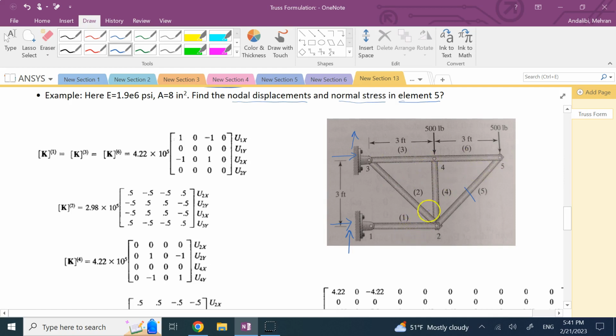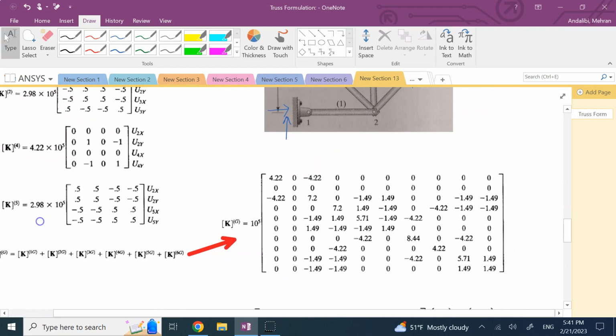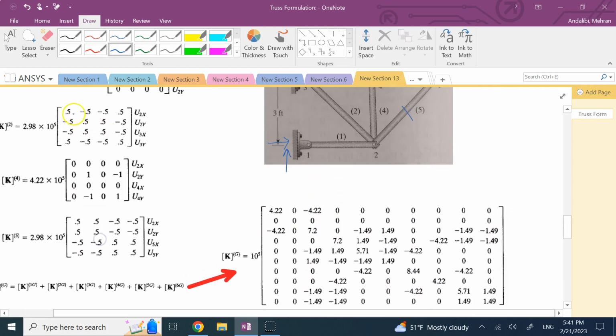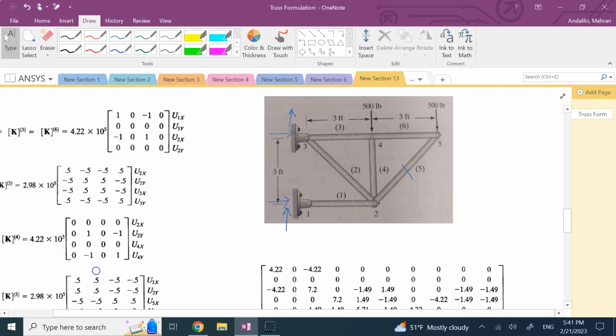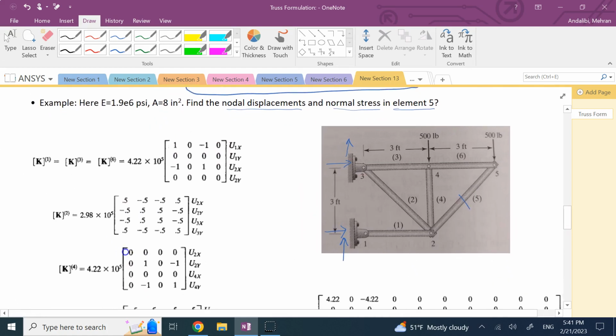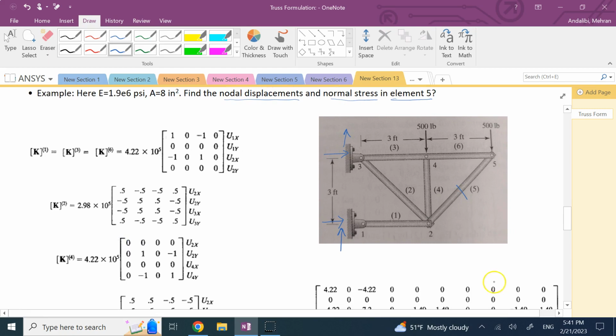If you want to write your own MATLAB code, or in ANSYS, the way it is used, or anything, it keeps track of the end nodes for each element. That's how, when you calculate the individual element matrices and you want to combine them into the giant matrix, which is for the whole truss, you know where each one of those components go into this big guy. If you don't know that information, there is no way you can put the truss stiffness matrix together.